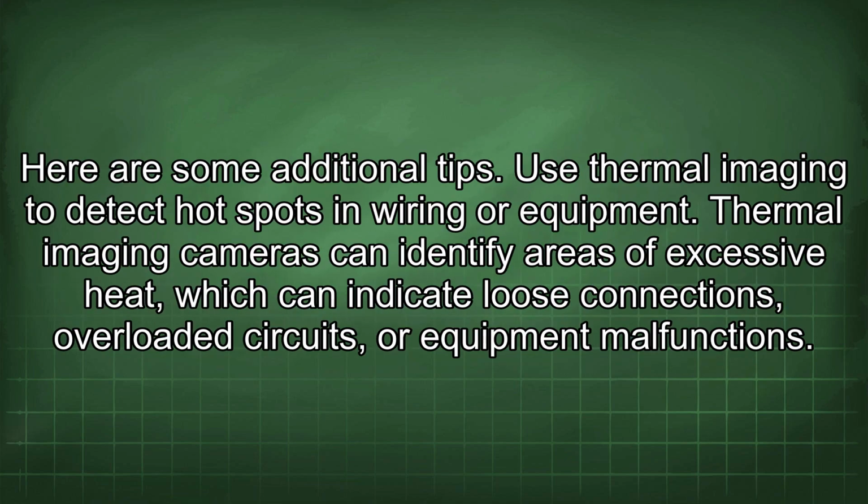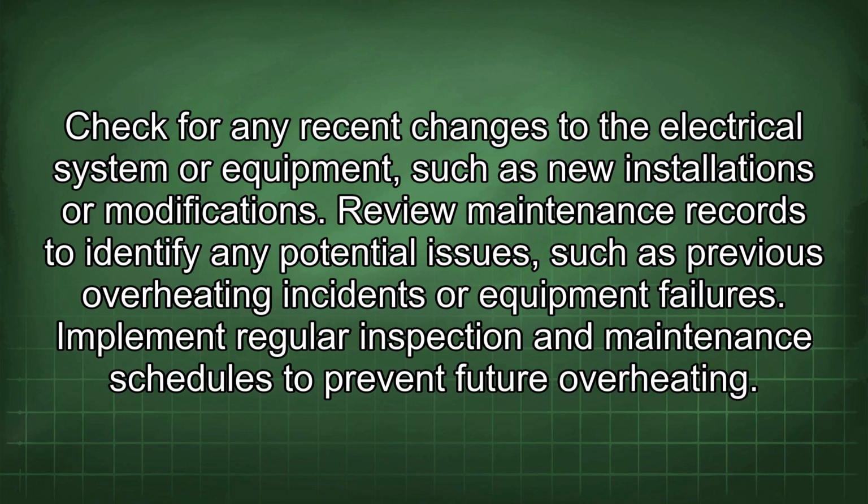Here are some additional tips. Use thermal imaging to detect hot spots in wiring or equipment. Thermal imaging cameras can identify areas of excessive heat, which can indicate loose connections, overloaded circuits, or equipment malfunctions. Check for any recent changes to the electrical system or equipment, such as new installations or modifications. Review maintenance records to identify any potential issues, such as previous overheating incidents or equipment failures.